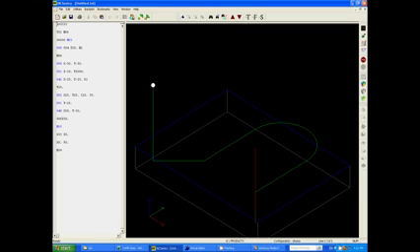So G code is supposed to be an ISO standard, however a lot of machine tool companies vary it slightly between one another, so you really need to get to know your own machine and how the G code functions on that.